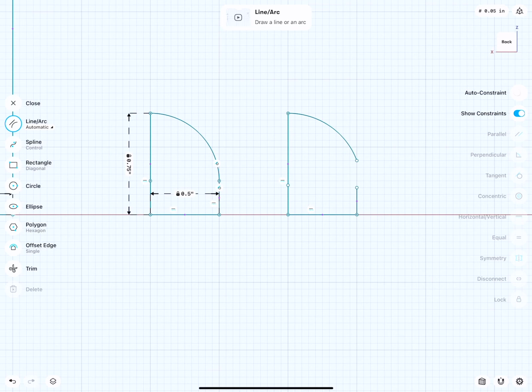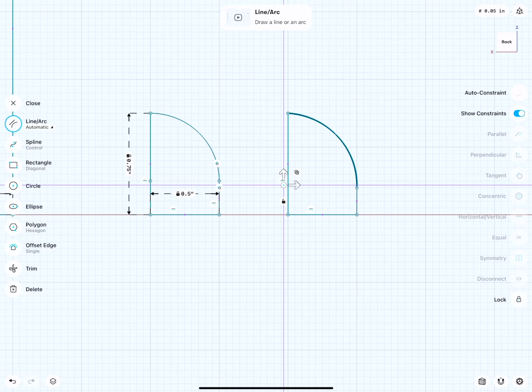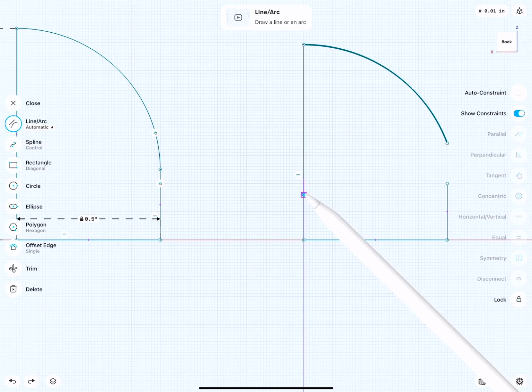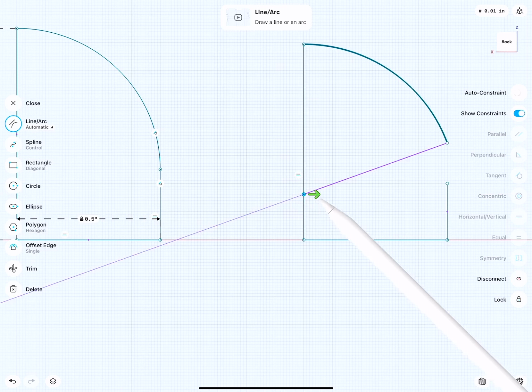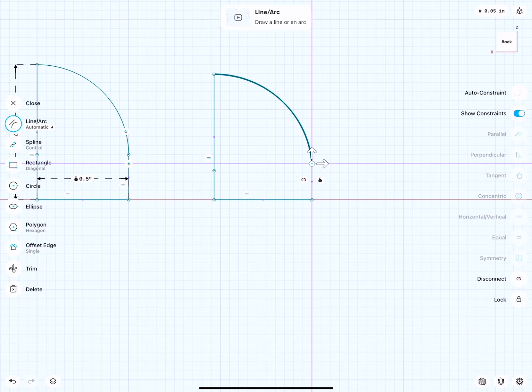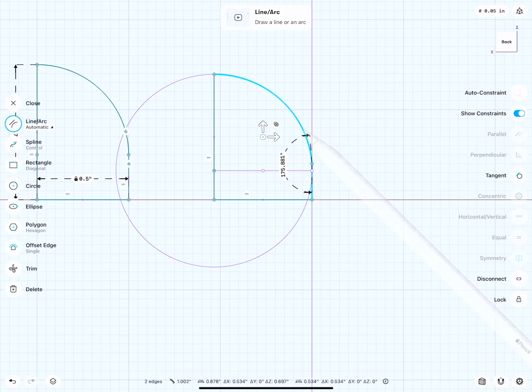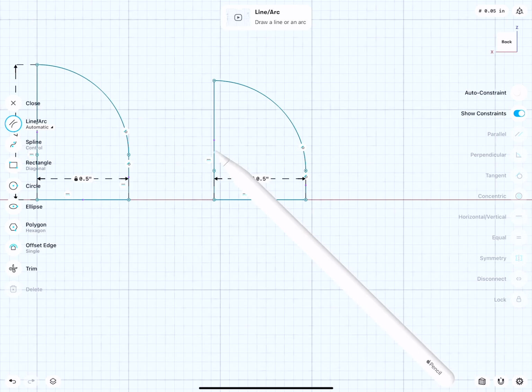The arc has a start and an end point. I can push this to there. Very good. And you see now the midpoint is outside. Now this point, move it actually on this edge and you will see, lower left or to the left of the lock icon, there is the coincident constraint. So now this arc center point is glued onto this line. Perfect. This point now I can drag onto this end point, select both tangent and then specify this 0.5,